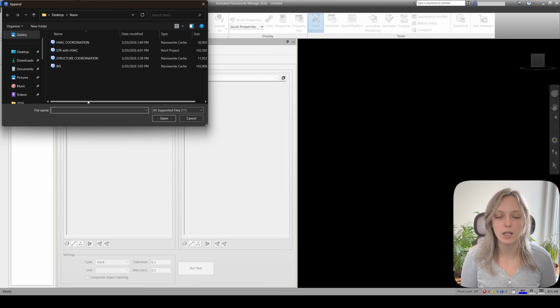So actually doing it model by model is much easier. Though it does seem like more work, you do want your work to be controlled. You do want to have control over what you do. So I do recommend doing discipline by discipline. For example, if we start with structure, you first want to do structure and mechanical, then structure and water and sewage, then structural and electrical, etc.